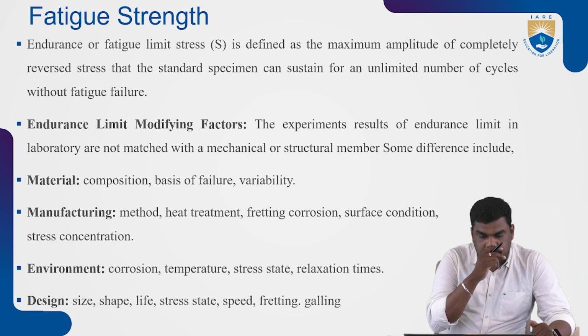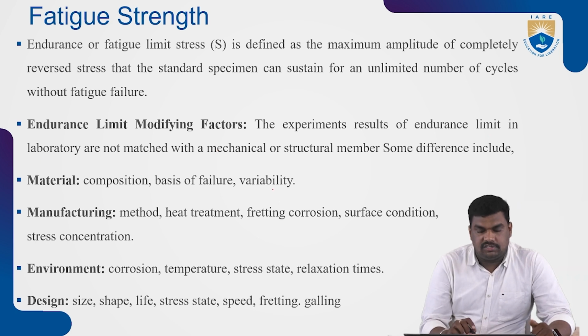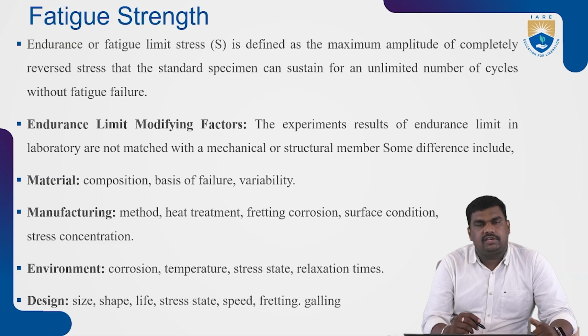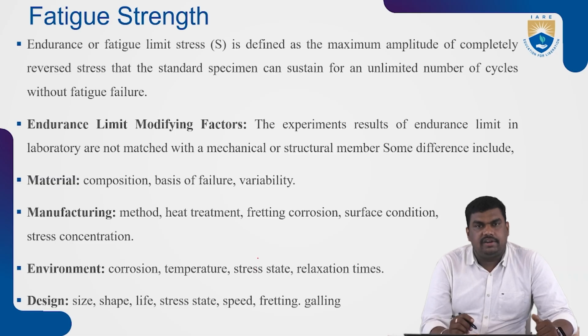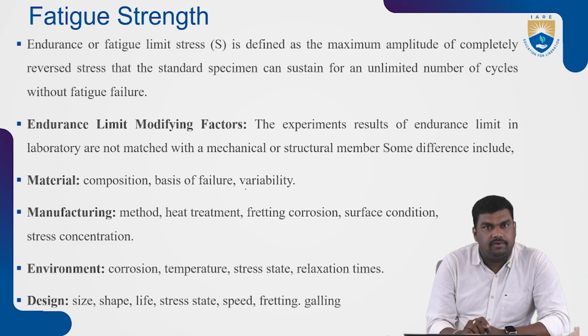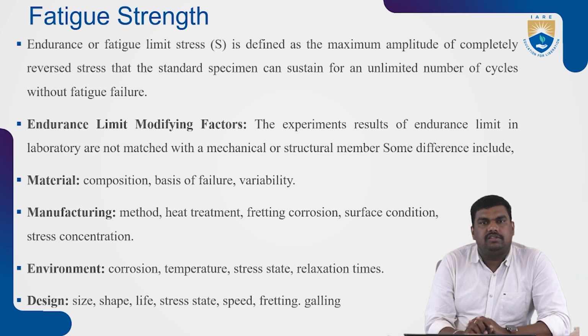So, endurance limit modifying factors. The experimental results of endurance limit in the laboratory do not match the mechanical or structural member, so theoretically there will always be different values. When you come to the practical, multiple modification factors are experienced. So for the fatigue strength, the endurance limit will be modified by different parameters: material composition, basis of failure, and variability in manufacturing. Different manufacturing methods also give different strength and properties of the material.